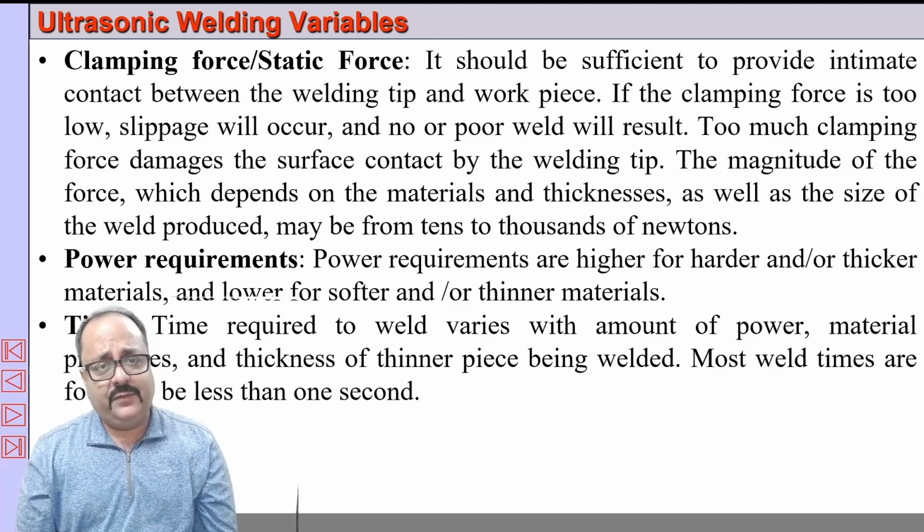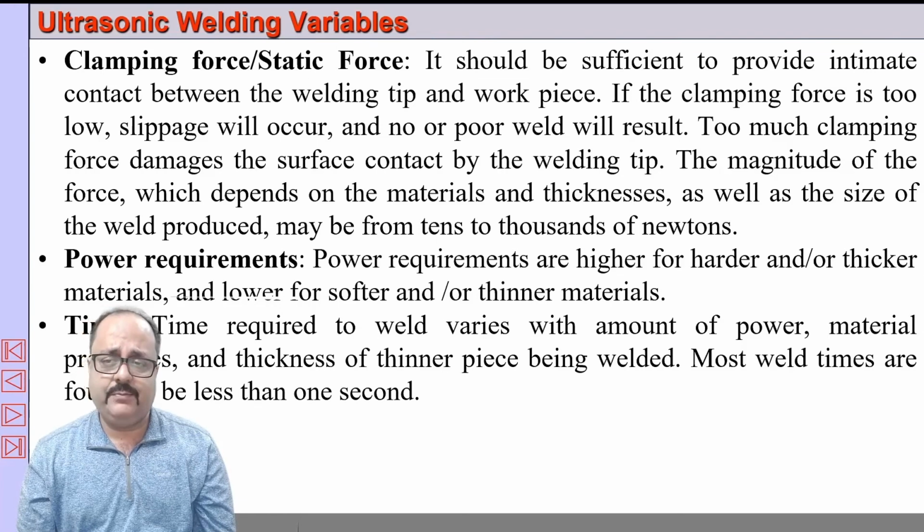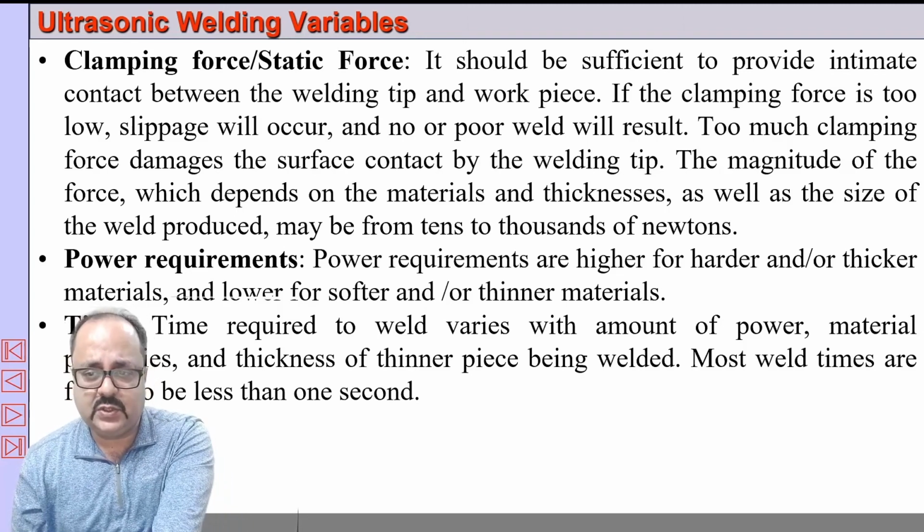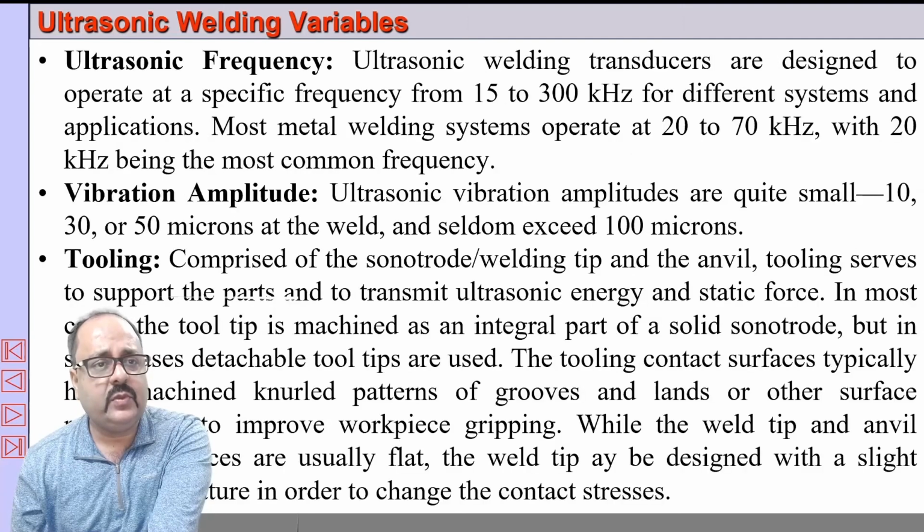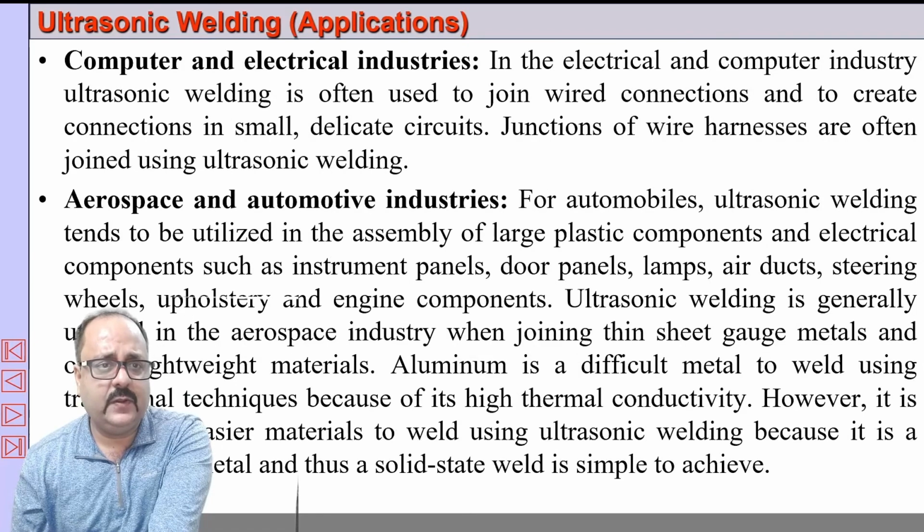Again, clamping force: you do not want to apply a high clamping force, which will create problems and lead to sticking. Also, you do not want too low a clamping force. So adequate clamping force is required, decided based on the thickness and the hardness of the workpiece. Also the power required, what should be the frequency of vibrations, and the exposure time are important. Vibration amplitude and tooling, all these are very important parameters in ultrasonic welding.